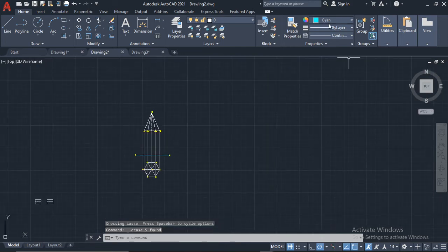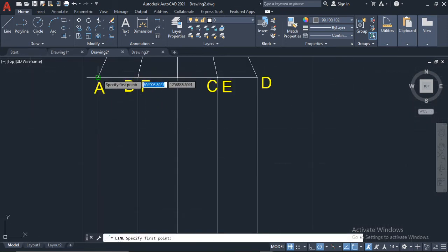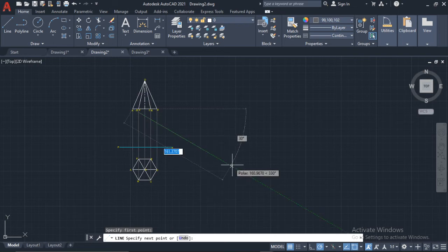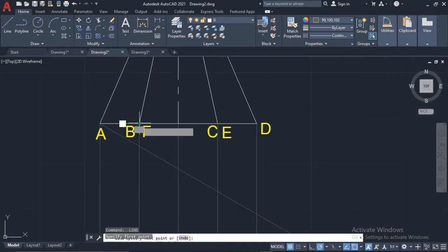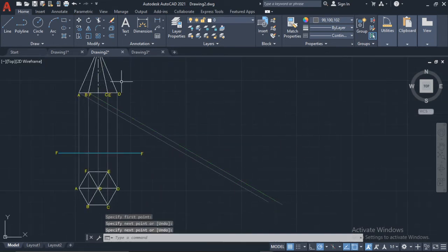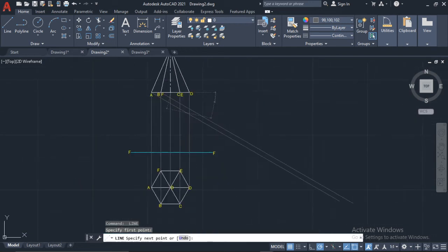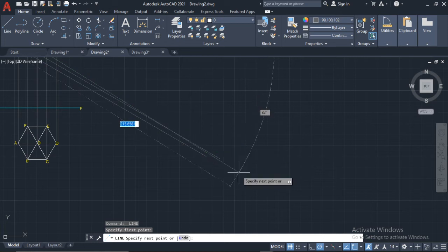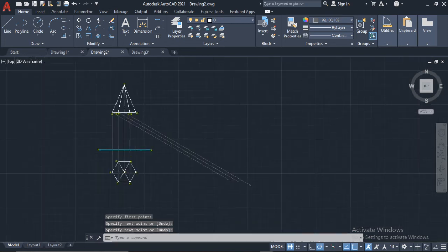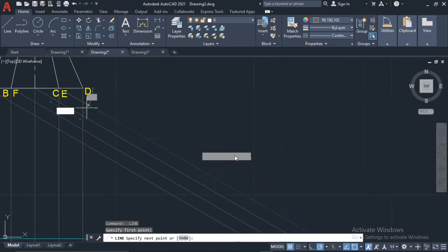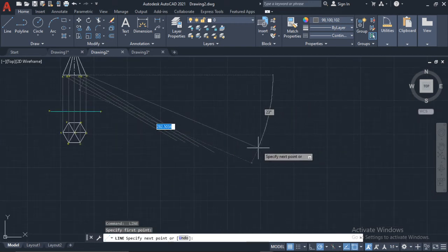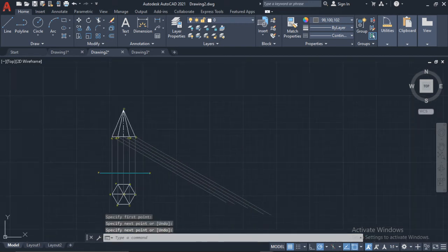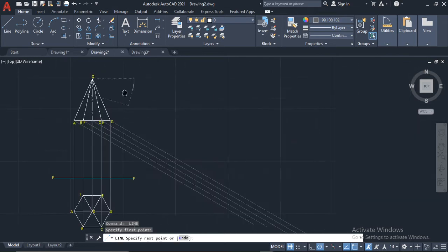It's just troubleshooting. When you're drawing, you'll come across different problems, but when you have that instinct, you can look at a drawing and tell that something is off. So I'll bring these out at 30 degrees actually. Yeah. And it would make sense. I think I had said that if the bisecting line is 60, then these lines would be 60, but it wouldn't make sense because for it to be perpendicular perfectly, we need it to be 90 degrees, and 60 plus 30 gives us 90. So yeah, it would make sense for these to be at 30 degrees. So I'm just bringing these down at 30 degrees. And then I'll bring this down also at 30 degrees.